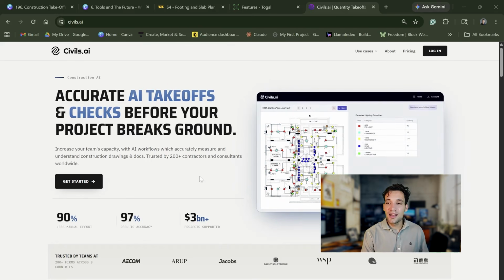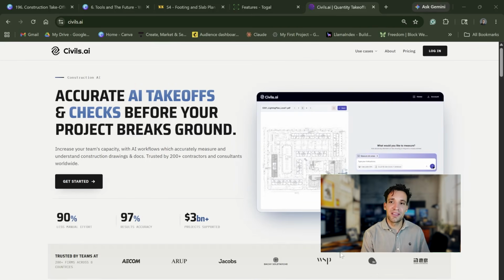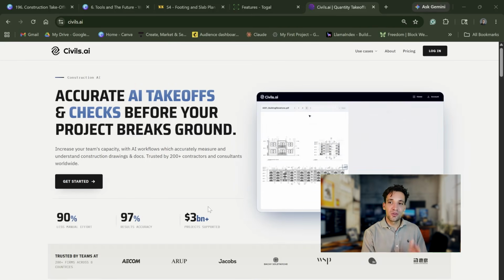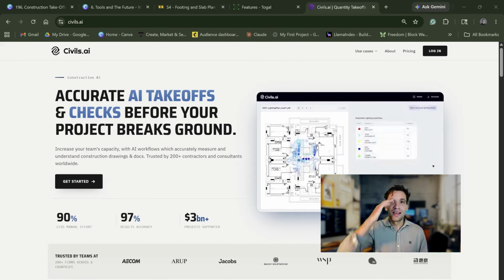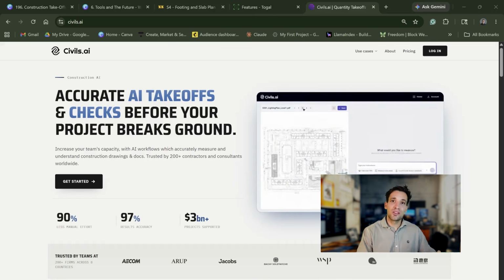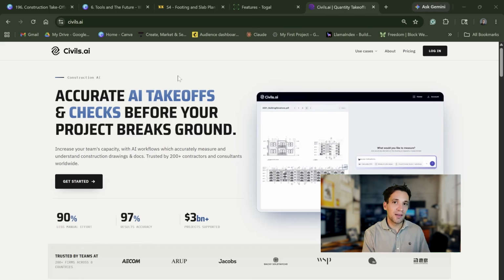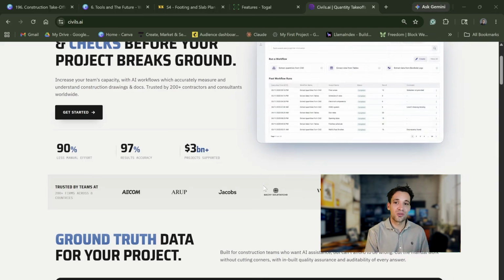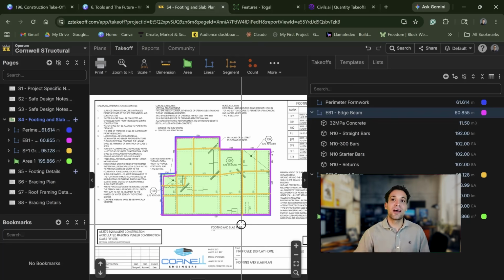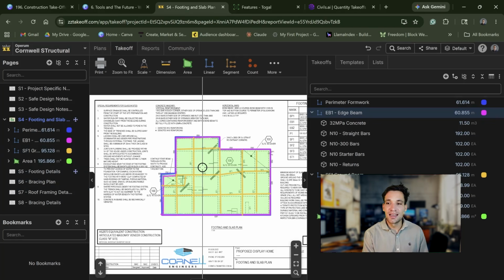But again, I think a lot of these tools probably overrepresent how much time it actually takes to do the physical counting. So much more of the time spent doing a takeoff is actually understanding the construction drawings and the scope. That is something I am hesitant to automate, because even in that example I gave before, cable tray on the ground versus cable tray mounted in the ceiling, I don't believe these tools pick up things like that. That is only information you get from properly analyzing and understanding the construction drawings and spending the time to work out exactly what you're building, what quantities you need, and all the nuances around those quantities.